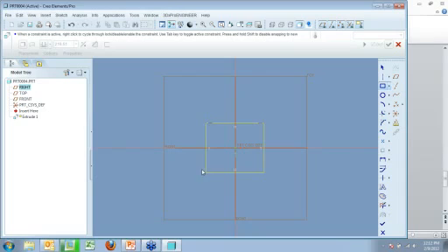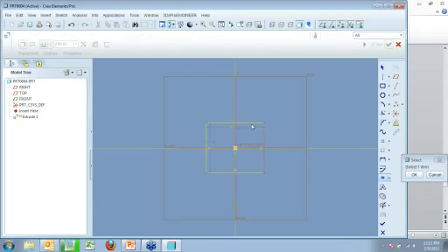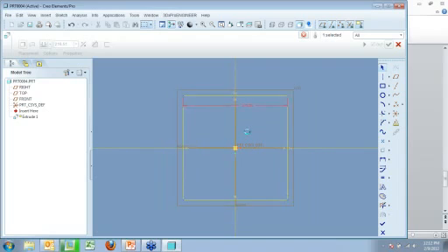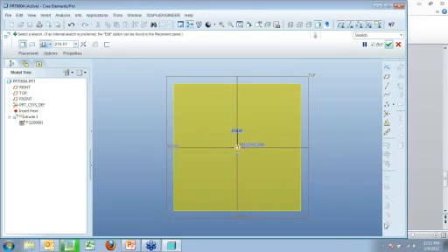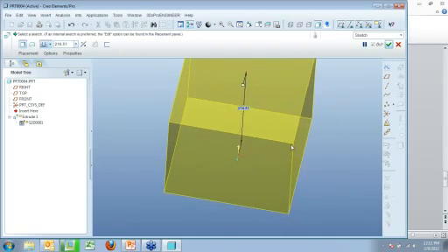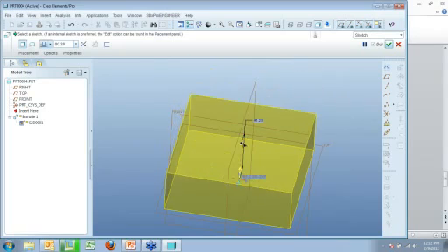Go in and get my square. Well, that's actually just a rectangle, so now I actually have to go in. Here's another couple mouse clicks. Make the 2 sides equal to each other. Go in and set this to 250. Now, select OK. See, I had to come all the way down here to click OK. Now, reorient and drag this to where I want it. We'll make this 100 tall.